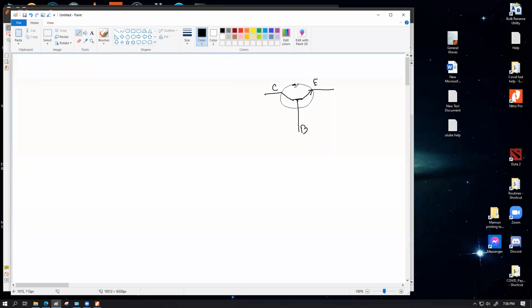The idea is that whenever there is even a slight amount of base current, the collector current and the base current will join up to produce the emitter current. How much current will flow from collector to emitter is directly related to how much current is allowed into the base. We have seen the atomic level discussion for this through an animation last class, so I'm not going to get into detail for that. We're going to see how we can use this component to our advantage in multiple cases.